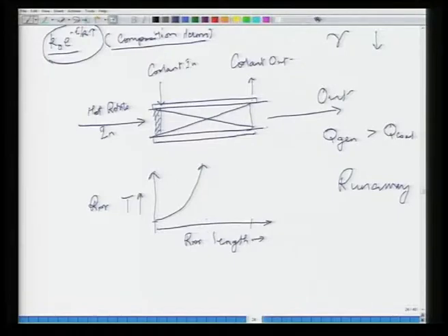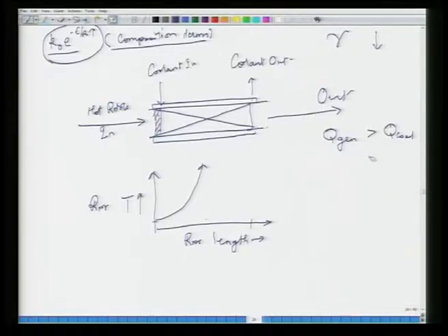Okay. So, therefore, what happens is the temperature essentially shoots up, and before you could get the hot spot where amount of cooling is the same as the amount getting generated, that hot spot temperature is so high, essentially what that means is that your reactor is burnt or your catalyst is burnt, or let us say some unsafe condition because of such high temperatures has occurred. So, a runaway is a condition which is actually a safety concern. Okay. So, if you have a highly exothermic reaction, I increase the temperature a little bit at the inlet, you can have a runaway.